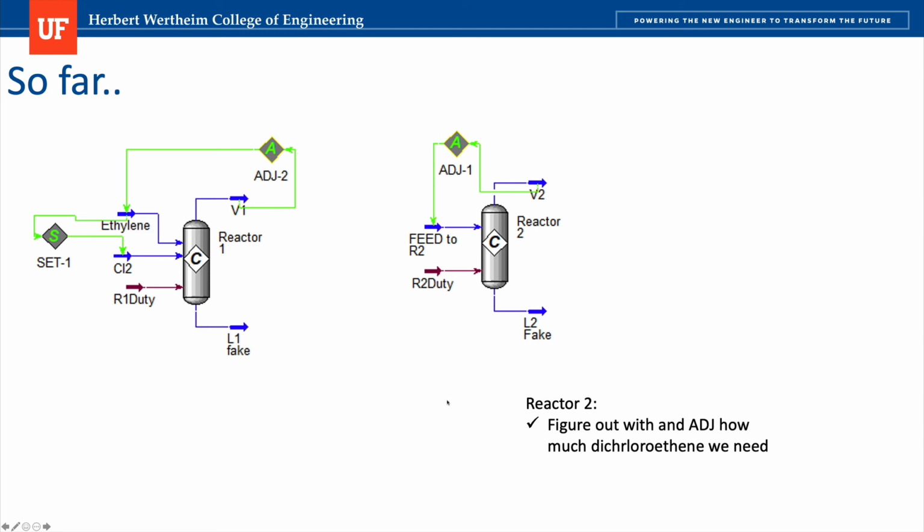Typically, you start with 1:1, or the stoichiometric amounts in the chemical reaction. And then after you do that and you add a recycle, probably it will be in excess if you don't allow the fresh feed of the reactants to be adjusted or modified as you add the recycle.